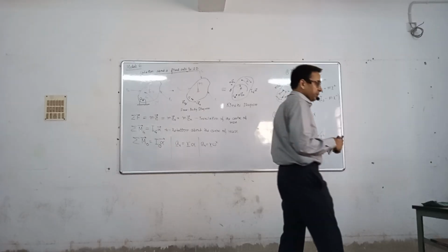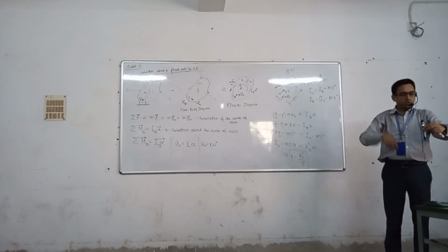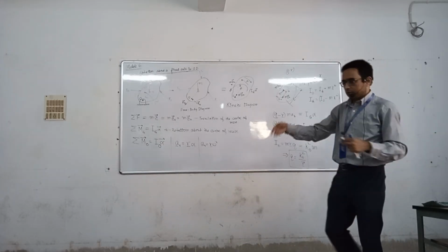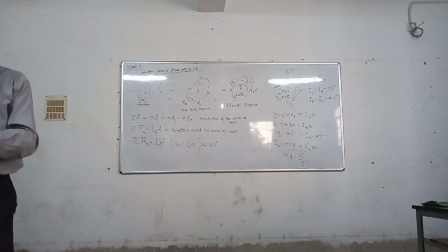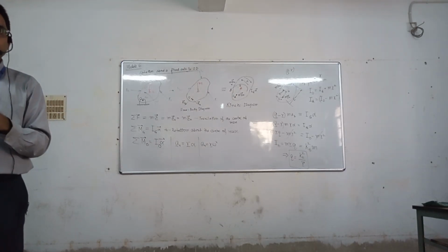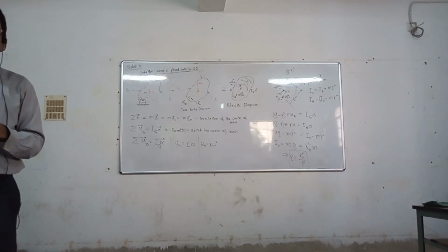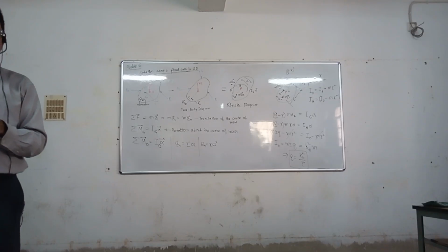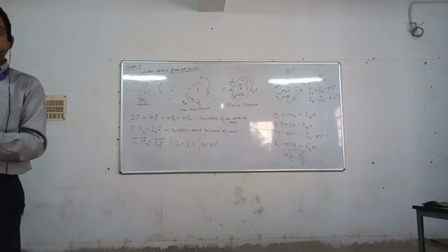Say, for example, there is a post that I have to set in the floor. If I strike at the center of percussion, then I will not feel any pain in my hand, or there will not be any reaction tangential to the bearing. That means my hand will not be lifted, or my hand will not be shifted.